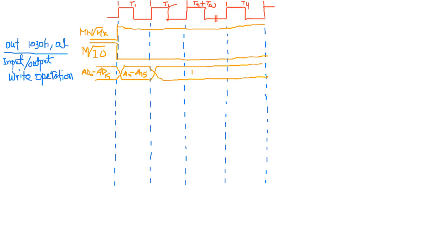And rest of the time it is for data. So there is no float mode here. One of the differences here, there is no float mode, because data is from the microprocessor. Data is put on the data bus. So D0 to D15. So during the T1 time, it is for address, and rest of the time it is for data. That's the main thing.